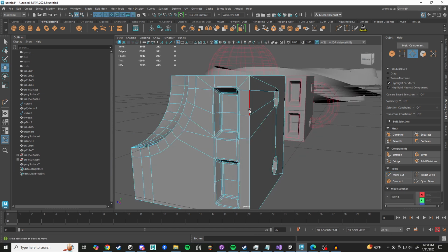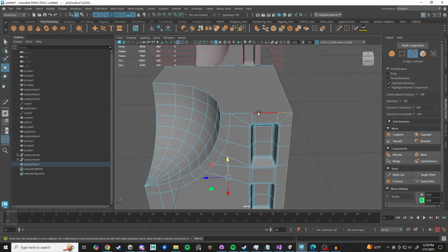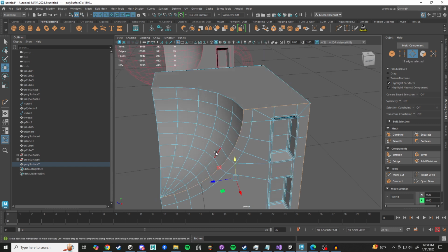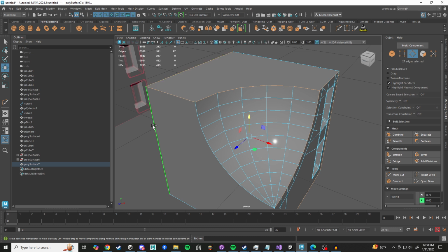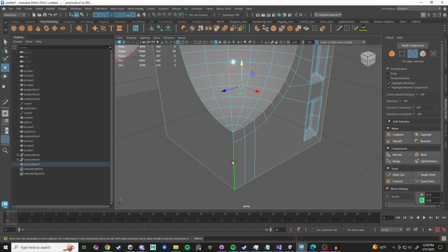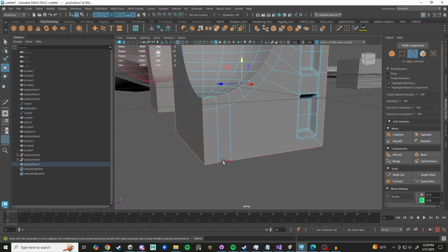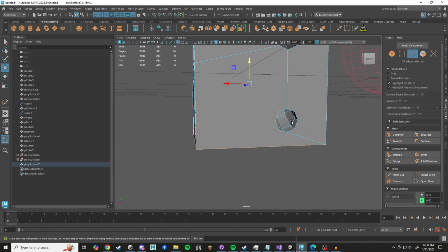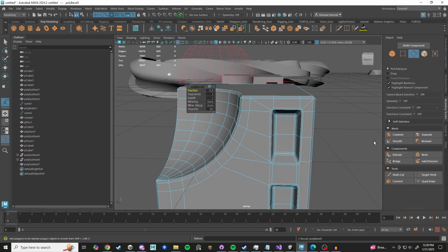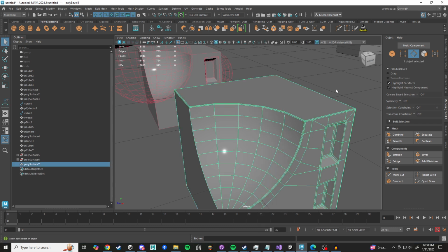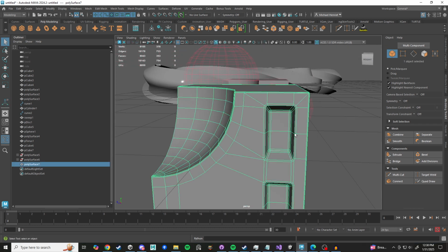And then I would also have to, after the fact, go through and bevel certain retaining edges. Yeah, let's just do these ones real quick, even though they're definitely n-gons right now. We do bevel. Let's do 2 segments, and let's shrink that. So now we have some retaining edge loops on a lot of those points.